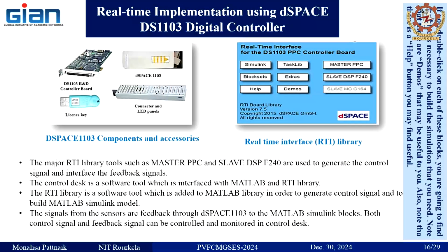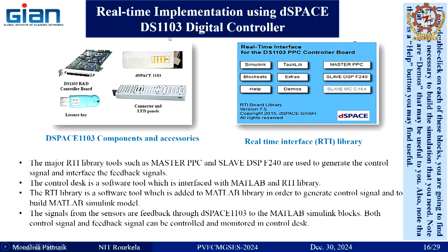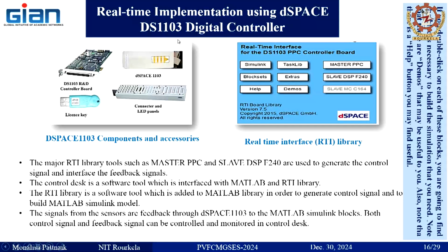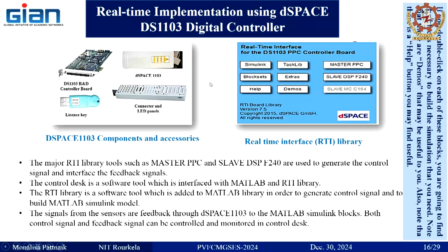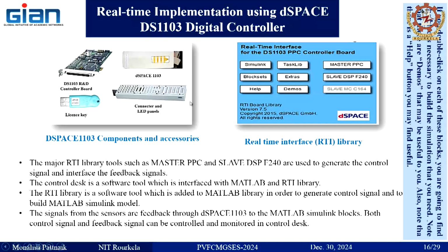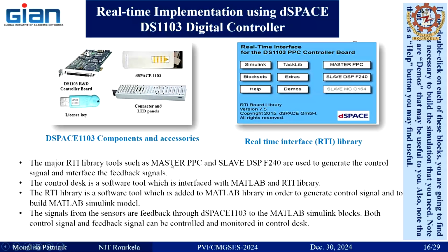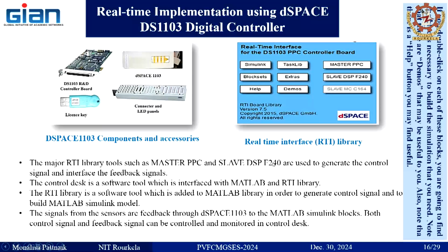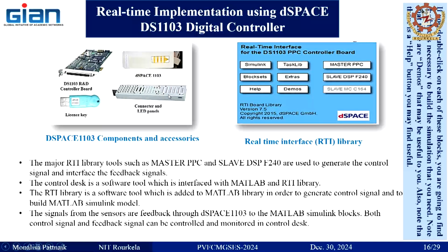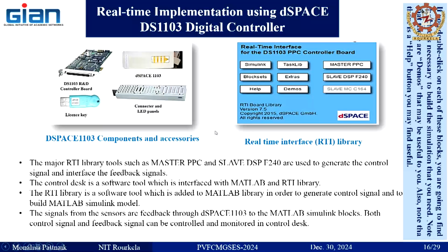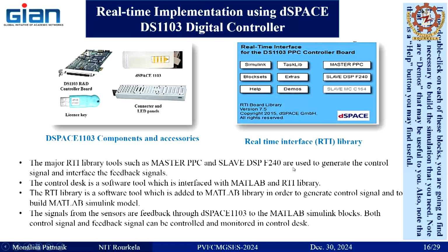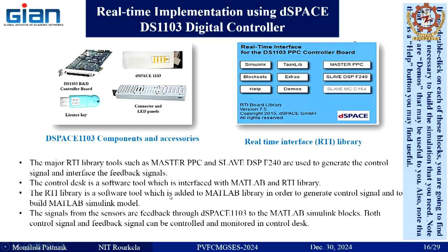So now coming to the controller part. For this implementation, we are using the dSPACE DS1103 digital controller board, which has two processors, the master PPC and the slave DSP F240 processor. These are two separate controllers, and we use them to generate the control signals for the switches.